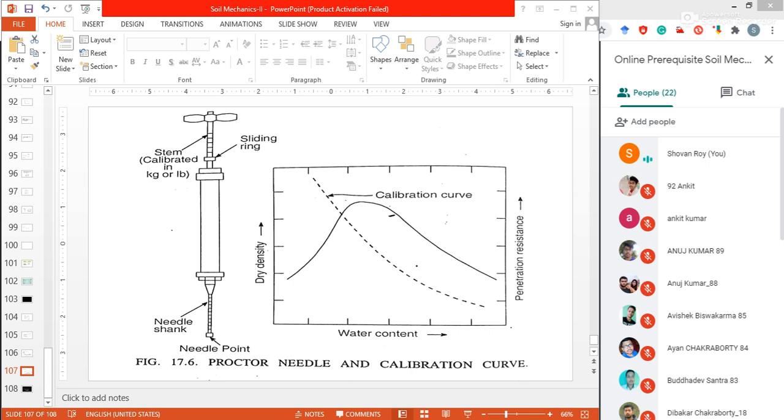In the calcium carbide method, or rapid method, 6 gram of wet soil sample is placed in an airtight container called a moisture tester and is mixed with a sufficient quantity of fresh calcium carbide powder. The mixture is shaken vigorously. The acetylene gas produced by the reaction of the moisture of the soil and the calcium carbide exerts pressure on a sensitive diaphragm placed at the end of the container.